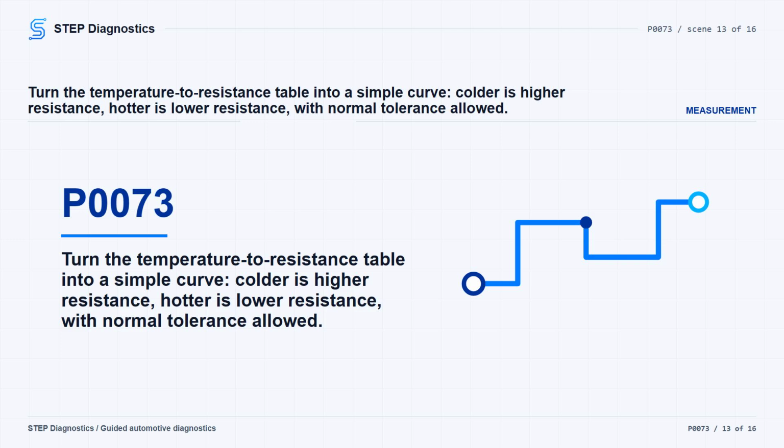If the actual sensor temperature can be acquired or reasonably estimated, measure resistance across the sensor terminals and compare it to the table. The table points include -40 degrees C, -40 degrees F, 345.26 k ohms as the lowest possible temperature reading; -10 degrees C, 14 degrees F, 53.38 k ohms as a logical temperature value; -5 degrees C, 23 degrees F, 40.89 k ohms; 0 degrees C, 32 degrees F, 31.56 k ohms;